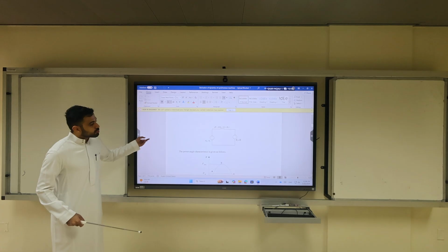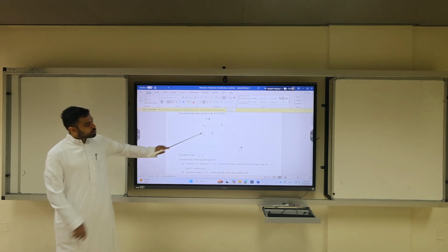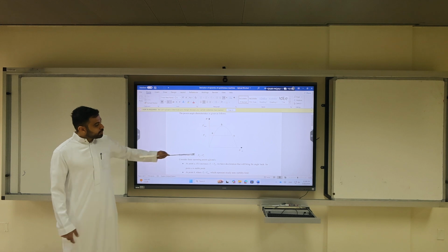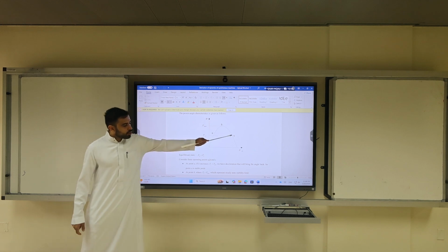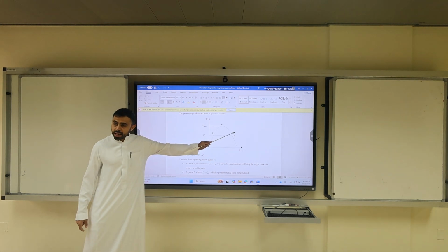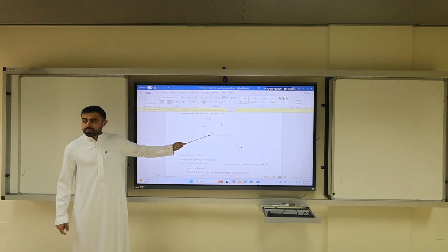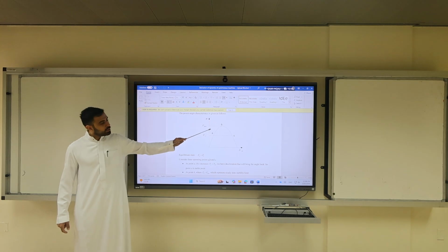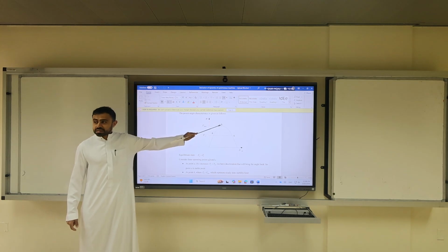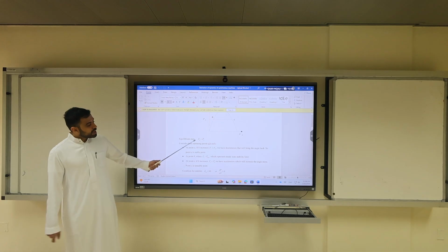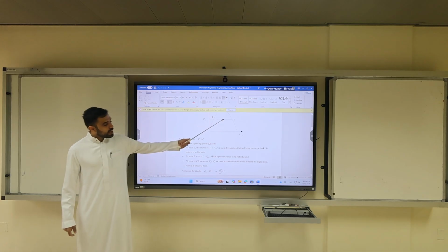What else we talked about? We talked about the equivalent circuit. We want to operate it, say, at region A at equilibrium, which is point A or C. C is equilibrium, but not stable. A is equilibrium and stable. B is not equilibrium, and this is borderline stability. Get it? And we claimed before that the mechanical power equal to electrical power at A and C.